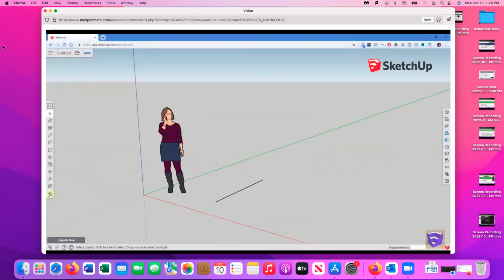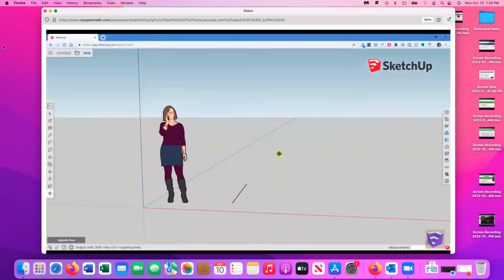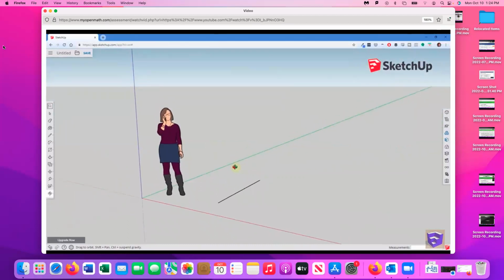The first is just to come over here and click on either these first person tools or the orbit tool right here. And you can see how there's multiple tools in here for adjusting your view and flying around with your camera in order to get to wherever you want to go inside the 3D model. For example, the first tool, and the tool you're probably going to use the most, is called the orbit tool. And so you can access that by clicking on this button right here and clicking on the orbit tool. You can see how when you do that, you can then click and drag your left mouse button in order to fly around and orbit around.